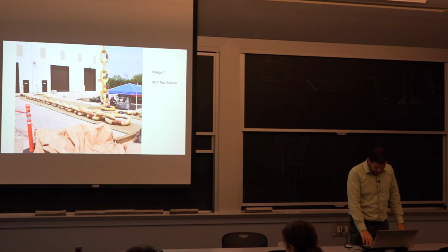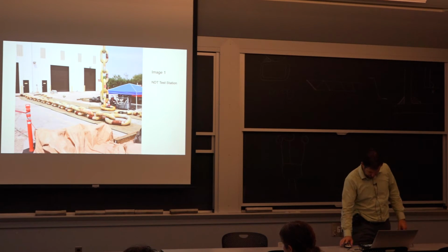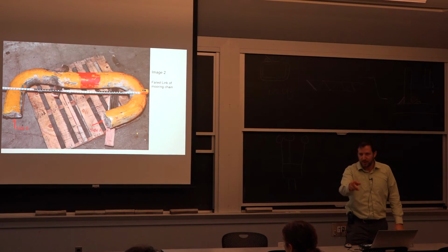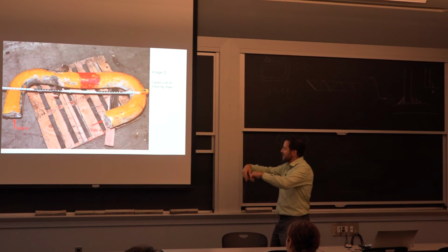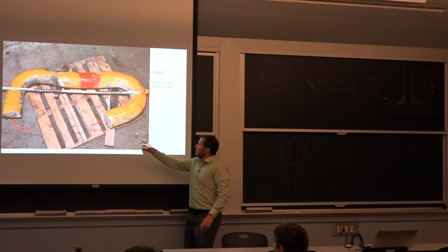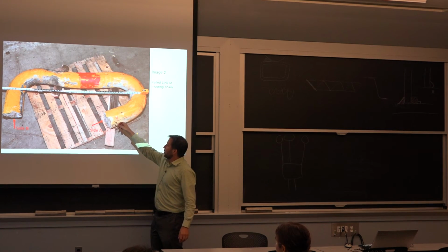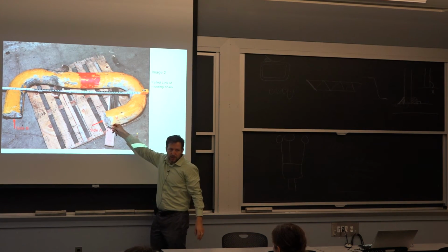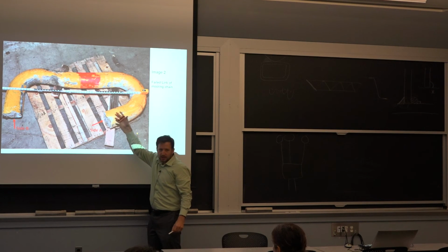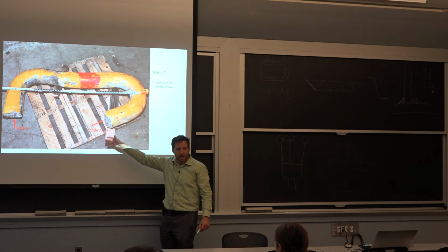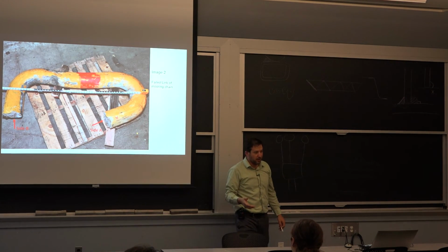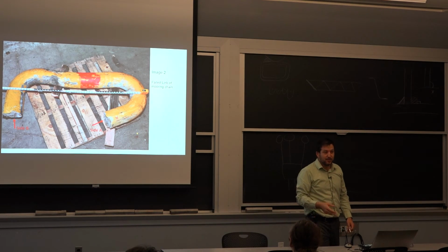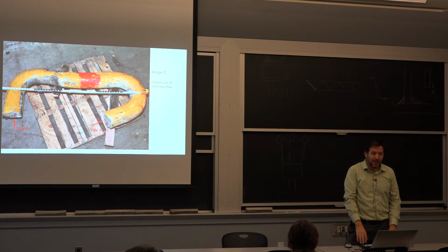The chain is only as good as its weakest link, right? So one of them broke, a little bit like your carabiner. One side and then the other side lets go. So there's only one weld. If you remember the process, we started flat and we bent it so the weld was over here. And you can probably see it looks a little flat, just generally speaking. So we already know, yep, it somewhat has to do with the welding of the chain.